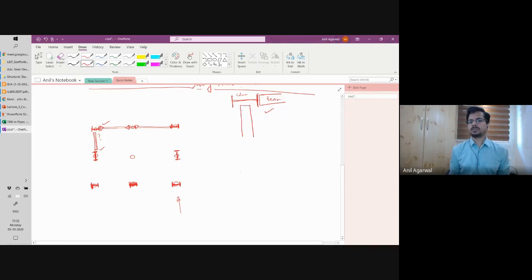Okay, and now sometimes the beam may not fit inside the column, but even if it does, even if it fits inside the column, is able to come within these 2 flanges inside. How do I connect this beam to this column rigidly? One way is to again connect the flanges of the beam to the column. Now I'm looking from this side. This is the column flange. This is the web inside. Okay. Let me go into the column.